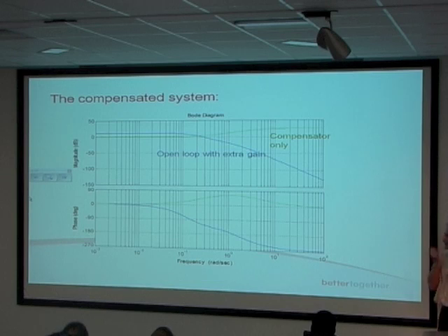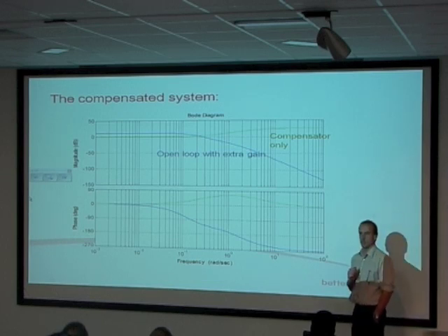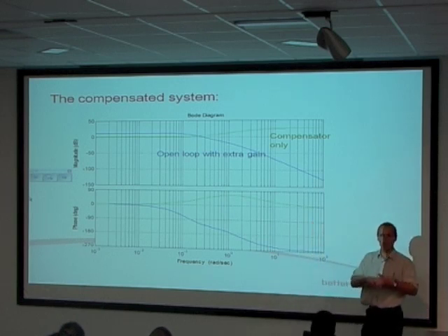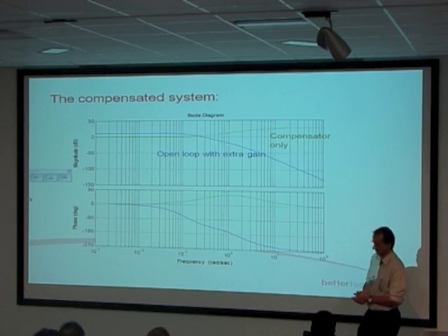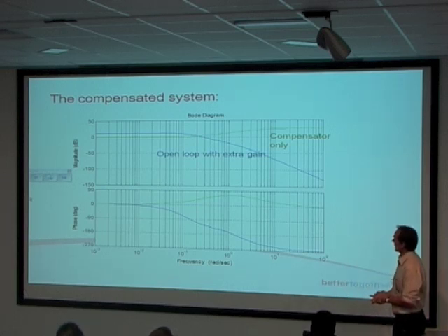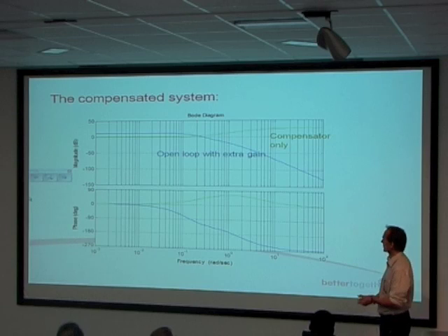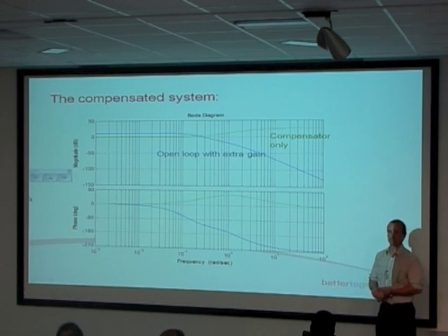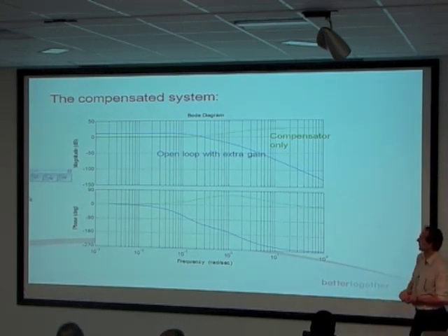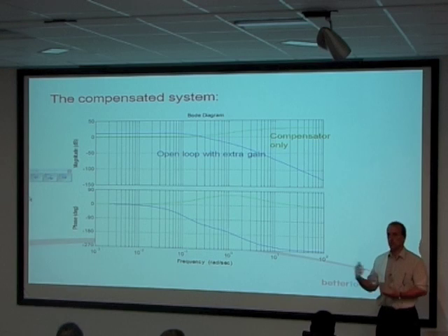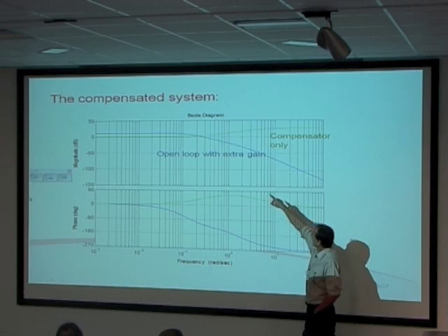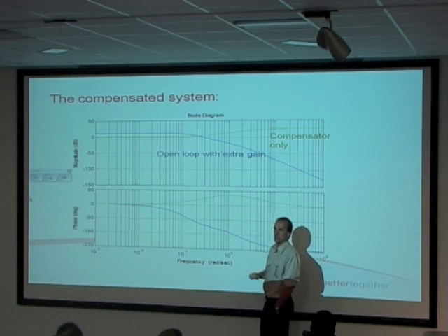Right, so let's see what the compensator looks like. So the blue one is our system, which is the submersible and its actuator, the open loop transfer function. And through the magic design process I'm not telling you about, I've decided that my compensator is represented by this green line. Okay, that transfer function that was given a couple of slides ago. And you can see it's doing all of those things that a lead compensator should do, kicking up the amplitude a little bit, and it's providing a bump of positive phase angle.